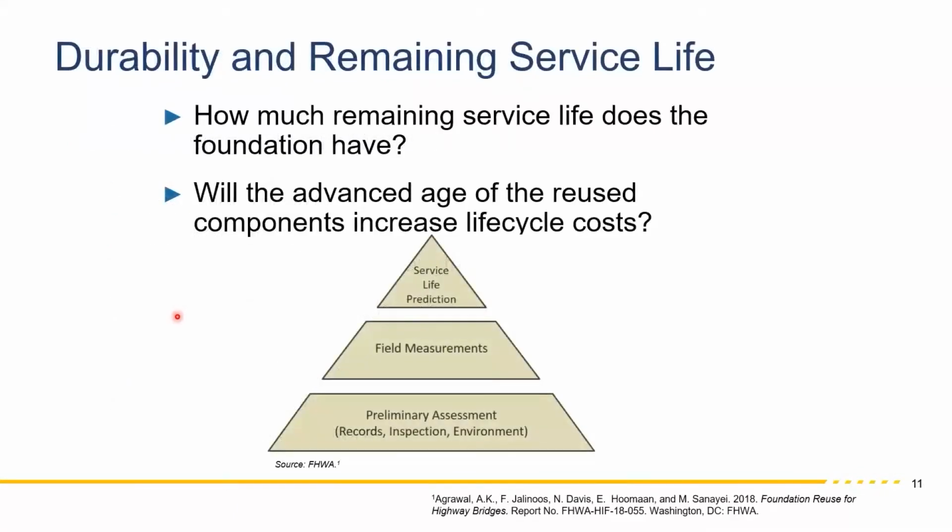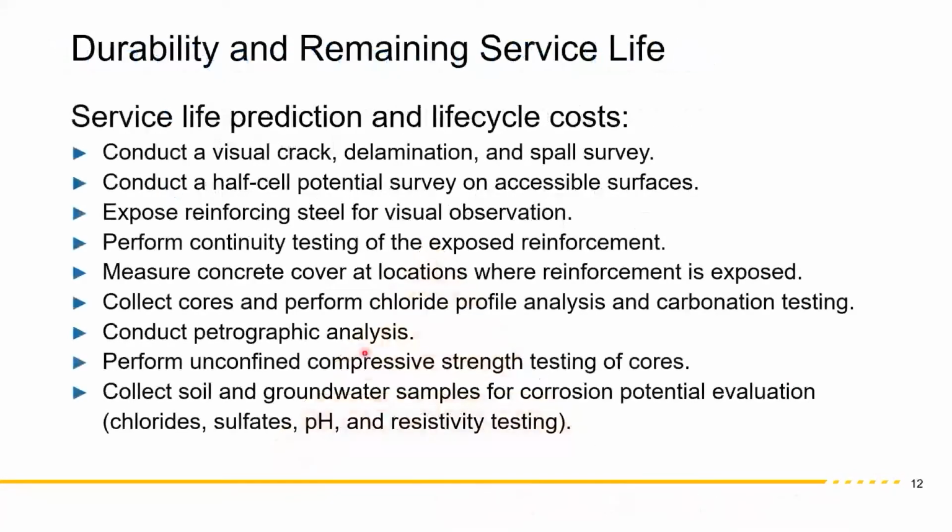Then the next thing you want to do is the corrosion study. So you start again by looking at the corrosion records on the elements that you're taking a look at. For example, you want to look at the piers, as in the I-95 projects. Then you go in the field and do some NDT inspection. That's the second step. And then the third thing you do is modeling for the remaining service life of the bridge member you're trying to reuse. So again, the process is you go out in the field, you first do a visual test.